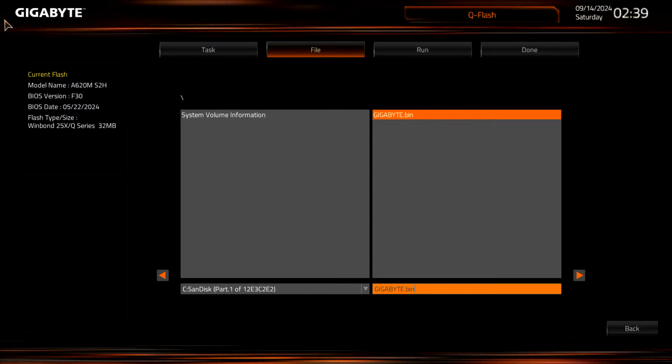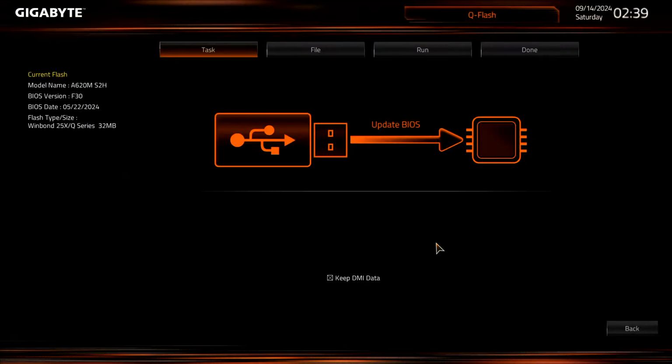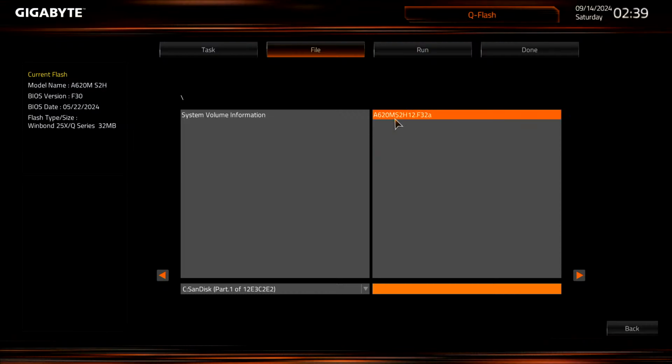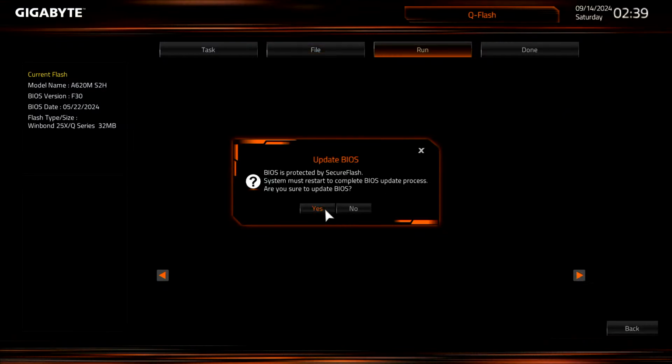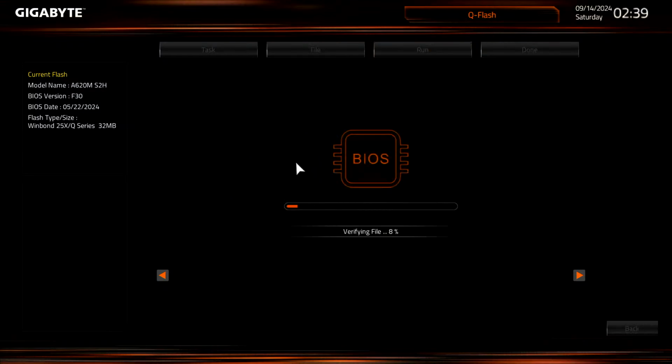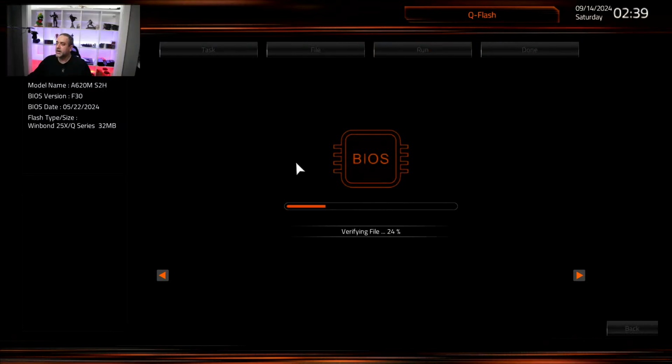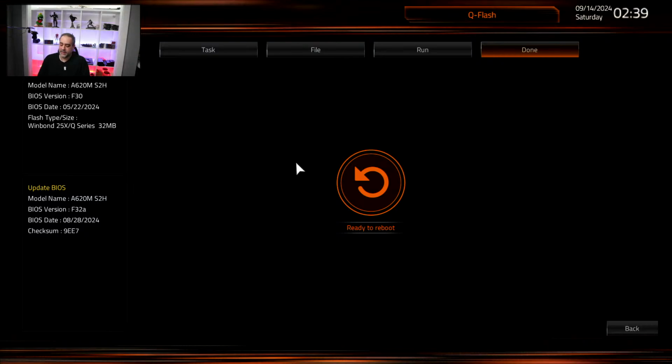Plug the drive back in. All right, and let me exit and come back, so it picks up the new drive. Yep. So we now have F32A again, the right one. By the way, if you noticed, it doesn't let you install the ROM BIOS. So it always has that ID check. If you get that ID check, then you know something is wrong. Obviously, the wrong BIOS. Could also be a FAT32 issue on the board. That is a possibility. It's rare, but it does happen.